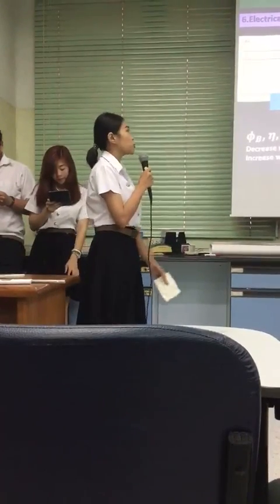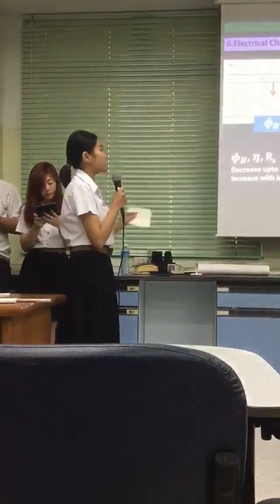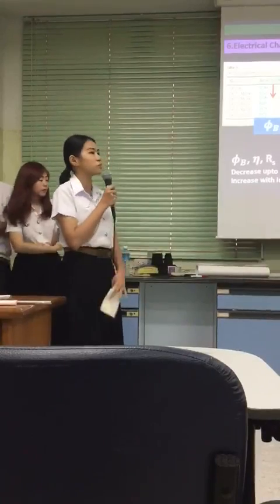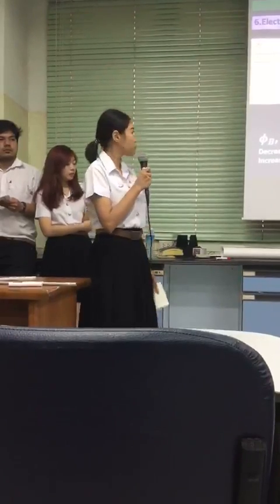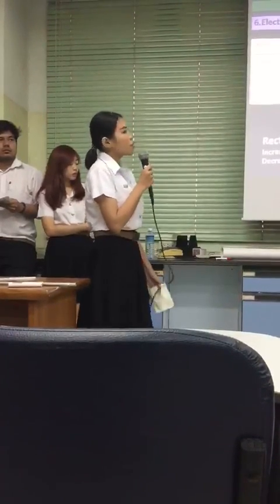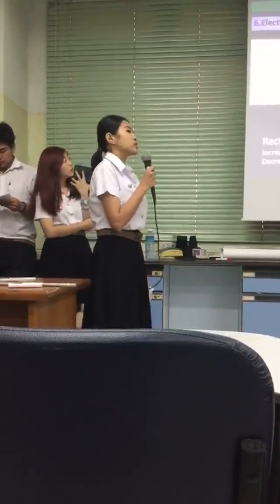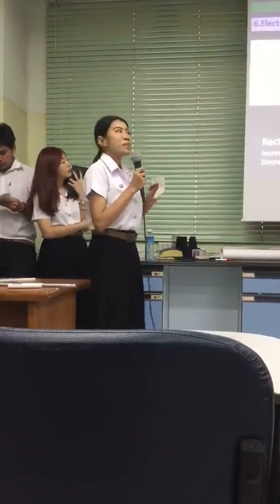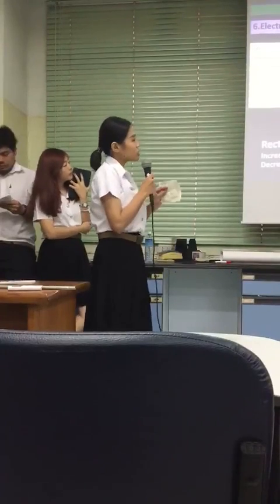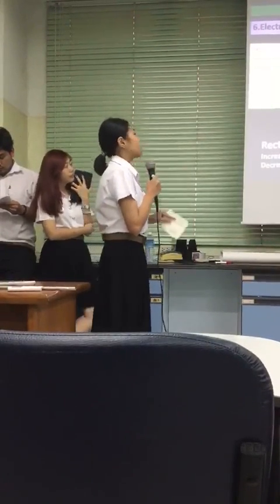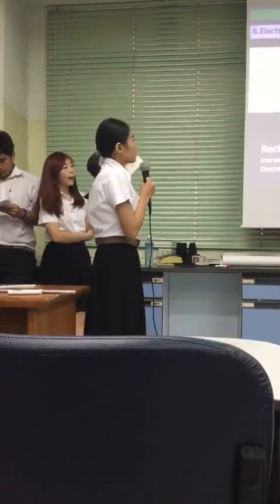This table contains the electrical parameters. The barrier height, ideality factor, and the series resistance decrease up to 3 atomic percent and increase with increasing magnesium concentration. On the other hand, the rectification ratio and reverse saturation current first increase with increasing magnesium concentration up to 3 atomic percent. Then for the 4 and 5 atomic percent of magnesium, they decrease.